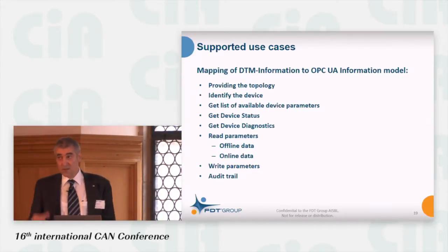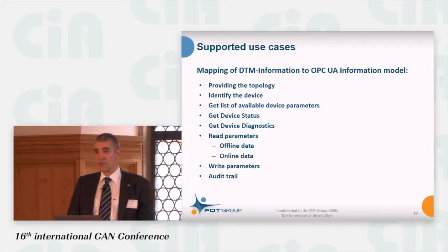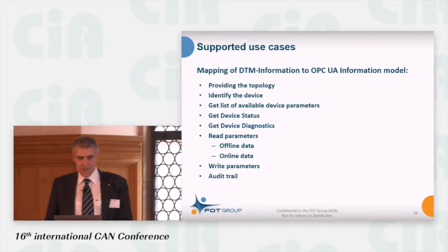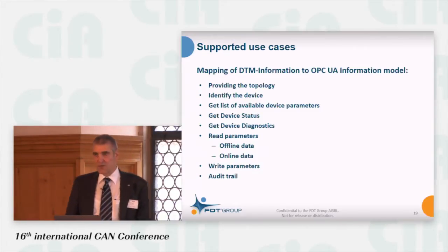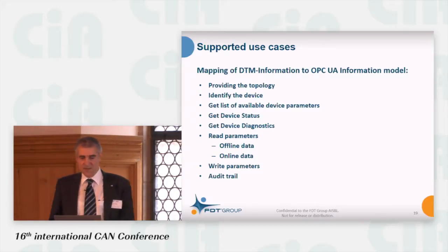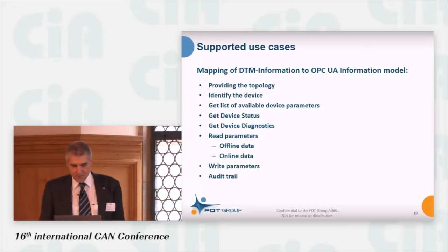That means you browse the OPC UA server to get all the objects out of the OPC UA server. We then have a list of the devices. We can identify devices. You can get a status or diagnostic. You can read and write parameters and all the things.